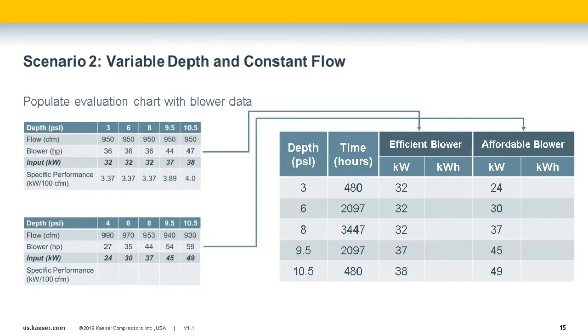Here, no interpolation is required. This is a fixed speed blower, so all we need now is the power consumption at each pressure, and this is what you would request from the blower manufacturer. It's as simple as entering your power values in for the required pressures. We can do this for each of the blowers, and we are ready for the next step.